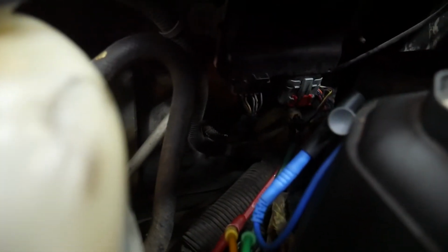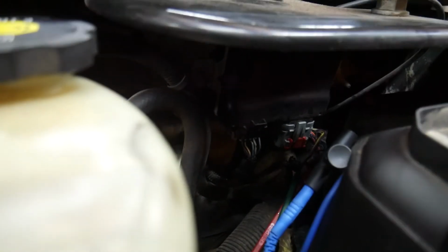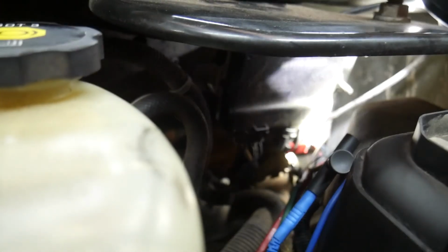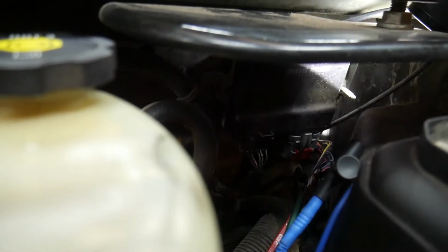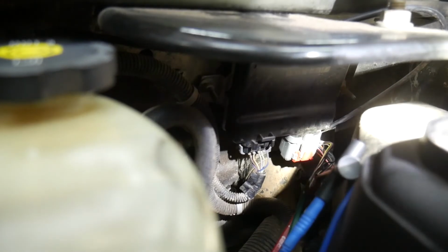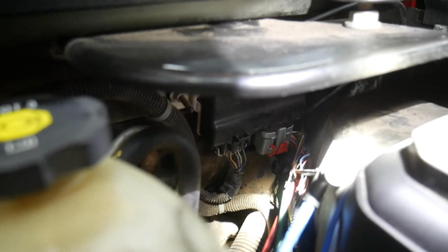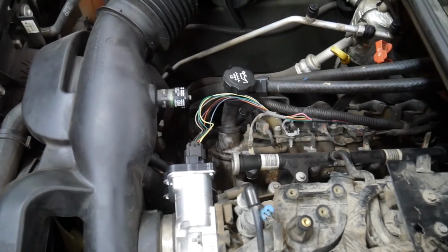So the throttle actuator control module is located on the firewall right back there. I know it's really dark. See if I can shed some light on the situation here. We're having some focusing issues, but it's right there on the firewall. The left connector is the one that goes to the throttle body. The right one is all the data lines and powers and grounds and everything else. The other shop already had the loom peeled apart for easy access. The throttle body is there with the pigtail exposed.